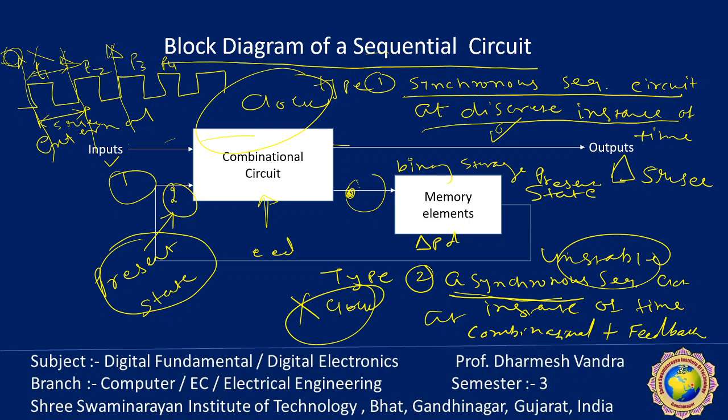The difficulty with a system of pulses is that any two pulses arriving from separate independent sources at the inputs of the same gate will exhibit unpredictable delay, will separate the pulses slightly, and will result in unreliability. Remember that practical synchronous logic circuits use fixed amplitude, such as a voltage level, for binary values. Synchronous means every system has a 5 volt master clock generator, which generates the periodic train. As I already explained, it is known as a clock pulse. Clock pulse is the name suggested for this particular master clock generator.